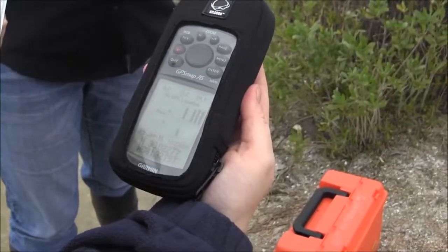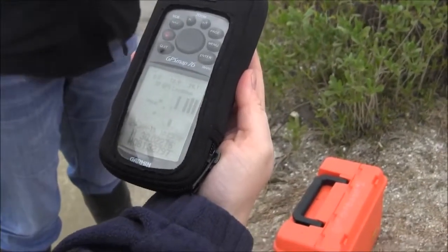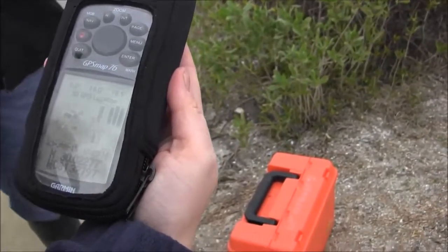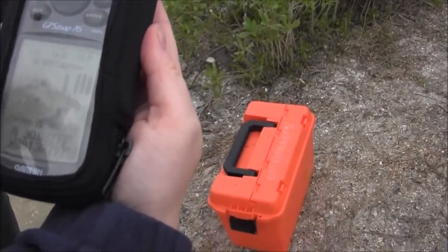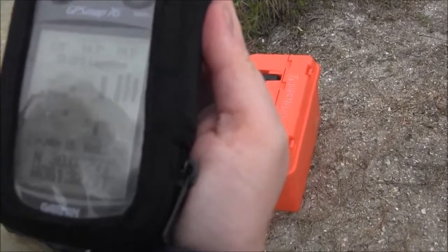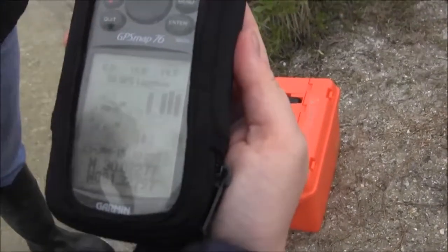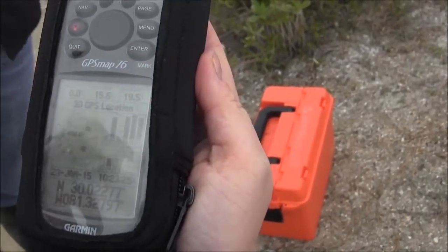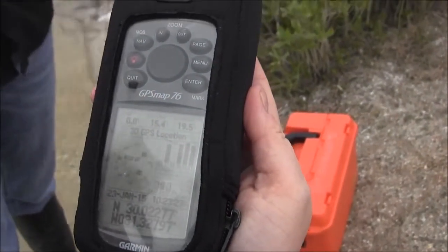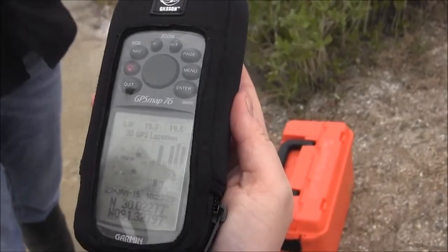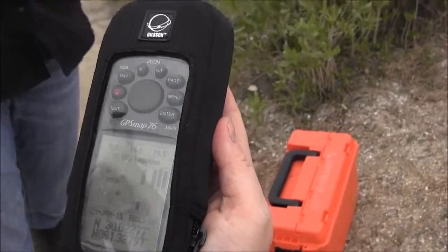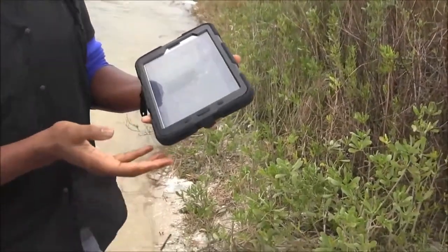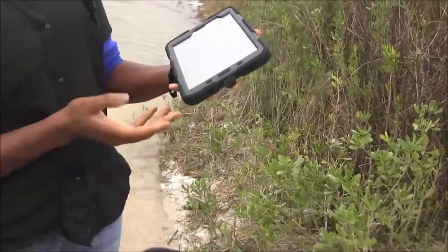Okay, so once you're out of your default screen, you're going to wait for the satellites to acquire the information, and it's actually going to send a signal down to give you your global positions. Once you have those positions, you're going to see 2 sets of numbers at the bottom of your screen. One has an N in front of it for north, and the other has a W in front of it for west. You want to write those numbers into your latitude and longitude spaces. So north or N will be your latitude, and west or W will be your longitude.